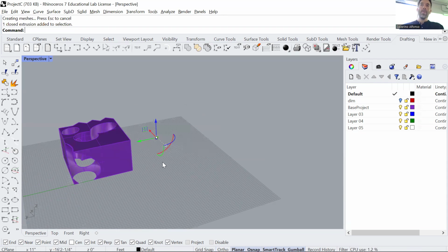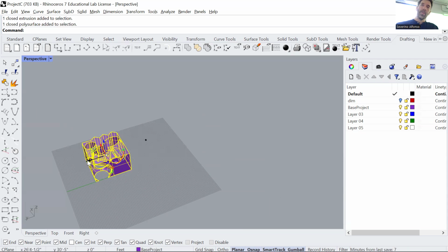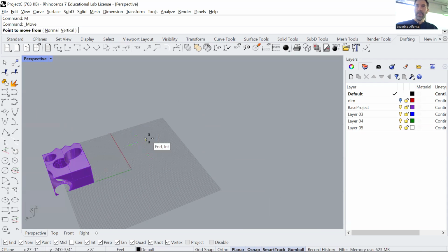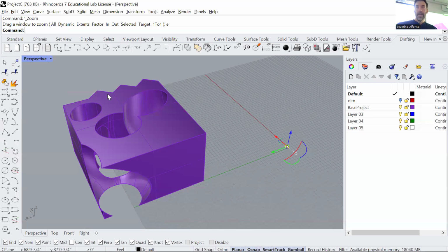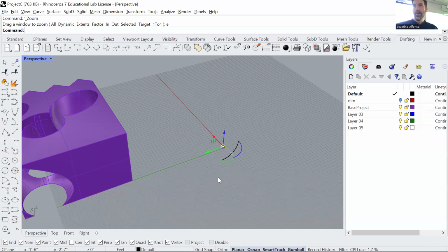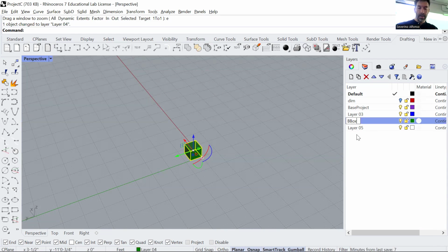You say, well, that's very small. Or what did you expect? That you're going to 3D print the entire building? Well, you can with some big machines, but it's not what we're going to be doing. We're going to do a very small thing. I recommend you have that bounding box, go to 0 and place it there, very small and cute. I would even call it something like change object, bounding box, 3D print limit, or whatever you want to call it. And that's the one you can turn off and on, so you can make sure that it fits inside.